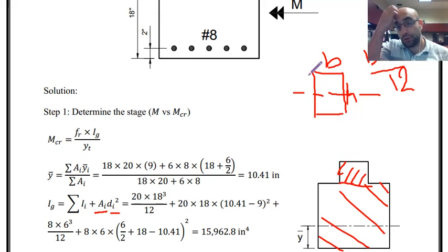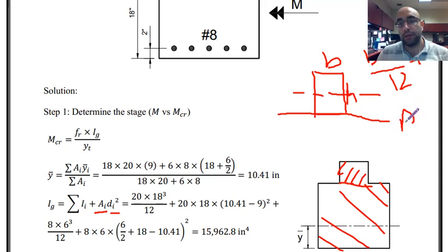If I want to calculate the moment of inertia, for example, about this line at the bottom of it, then I have to say b h cubed over 12 plus A d squared. A is the total area of this shape, which is b multiplied by h, and d is the distance from its centroid to the line where we are calculating the moment of inertia about.